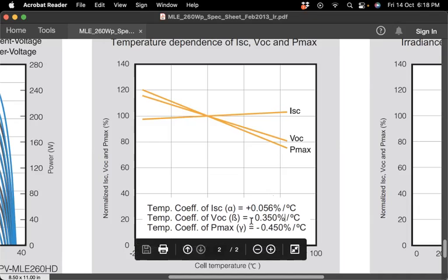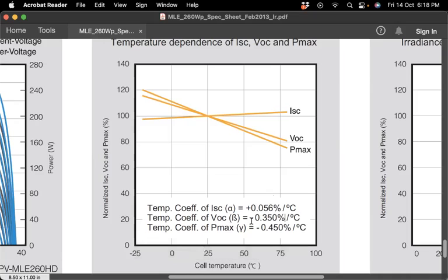This is observed with this gamma coefficient, which represents the variation of the power extracted per each degree Celsius increase in temperature. And that reflects what happens at this 2.7 sun, at 2,700 watt per meter square. At this point, the effect of the solar concentrators turns against your application because temperature effect dominates and your power starts to decrease more and more.